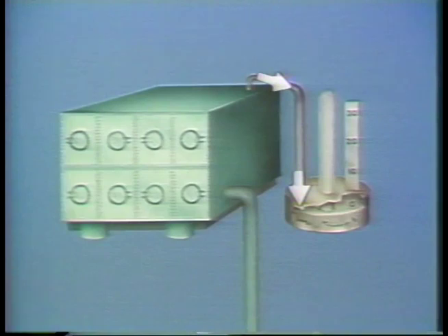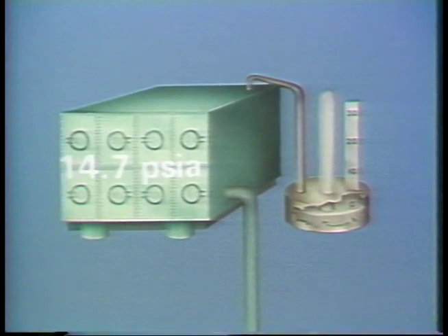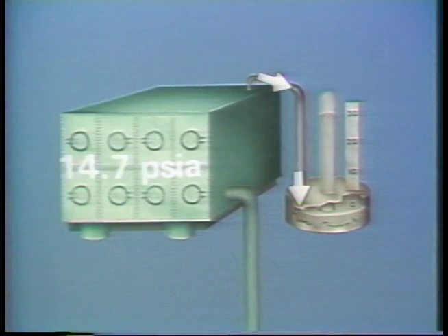Now, here's the condenser, and here is the manometer. And notice that the manometer looks a lot like a barometer, except the bottom is sealed and connected to the condenser. In this way, the pressure in the condenser pushes against the mercury in the container. Now, when the condenser is shut down and vented to atmosphere, there's 14.7 psia pressure in the condenser. Now, this 14.7 psia pushes down on the mercury and pushes it up the tube to a height of 30 inches. When a unit is started up, a vacuum is drawn in the condenser.